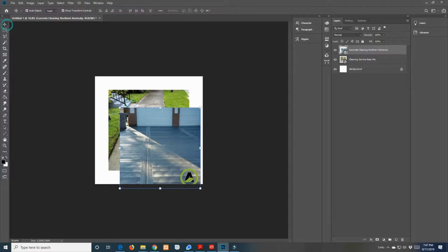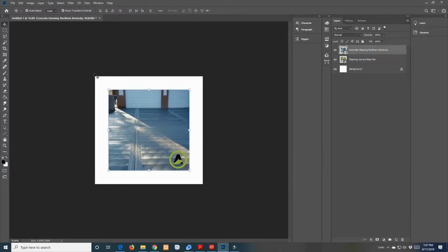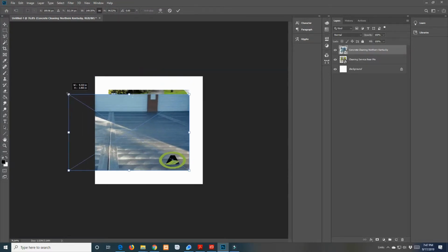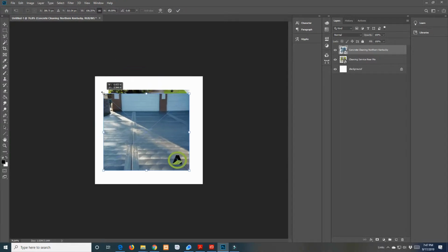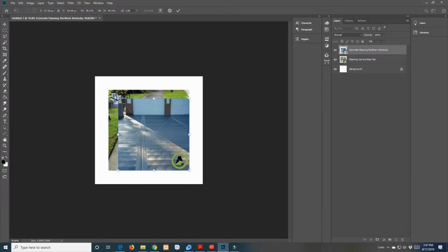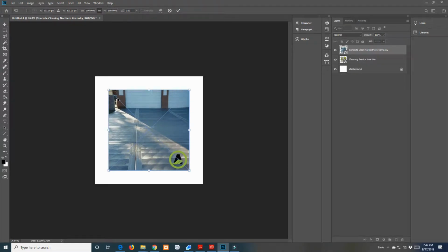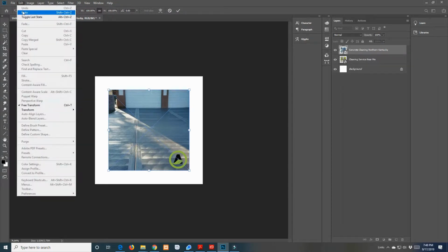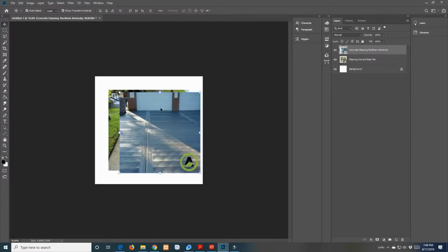Okay, so let's say we wanted to make this right here the full length, the 600 by 600. Well, watch this. Okay, so it's going to get all distorted if we just click and drag on a corner. So I'm going to hit Ctrl Z. Ctrl Z, something you're going to want to remember for sure. That is go back. Ctrl Shift Z will go forward. So if you went too far back, you can hit Ctrl Shift Z and go forward. And you can also just come up here to Edit, Undo and Redo, and you see there are the hotkeys again. So there's definitely a handful of hotkeys you'll want to learn, and it's going to make your life a lot easier.